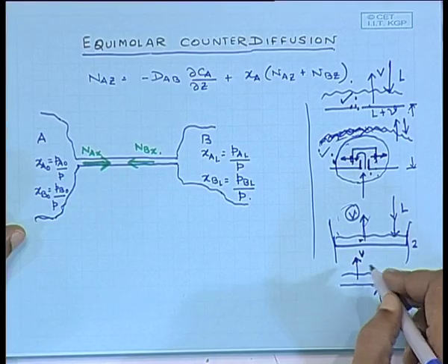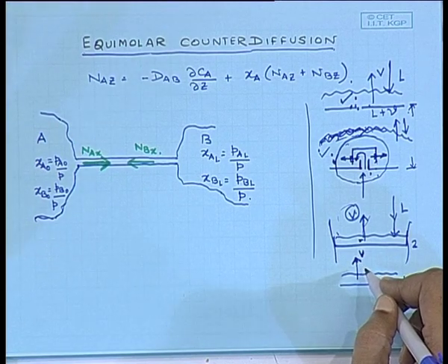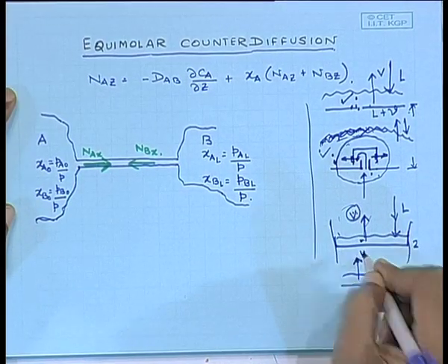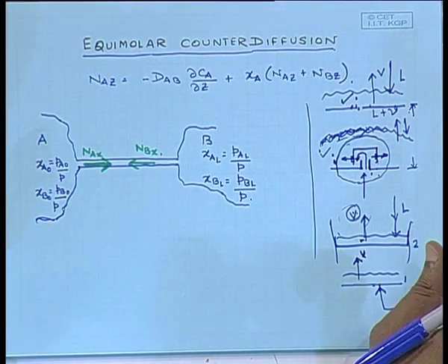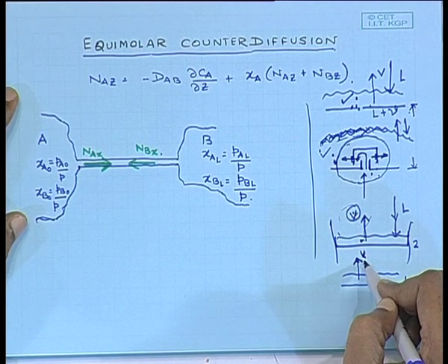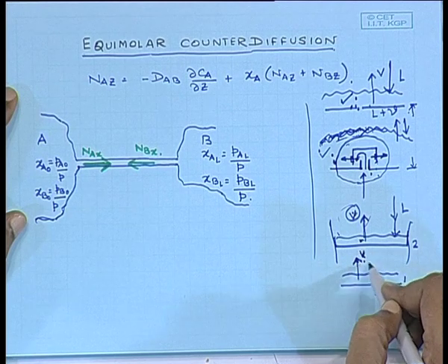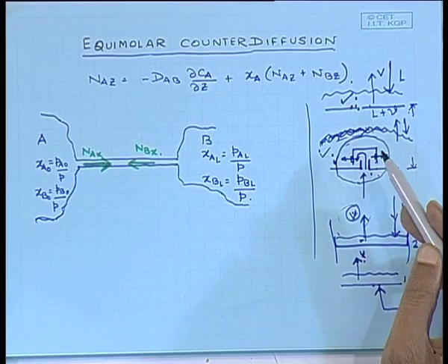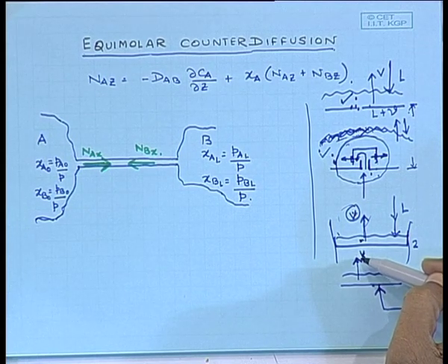The vapor which is coming contains, let us say, 2 components. It is the simplest possible situation, which is a binary distillation column, a 2 component mixture. Would the composition of these 2 be the same? Compositions are different. So, this is going to be richer in the more volatile component compared to this stream. Now, what is the latent heat of a stream? The simplest possible representation would be latent heat of component 1 multiplied by the fraction in which it is present in the stream, plus latent heat of component 2 multiplied by the fraction in which it is present in the stream. So, since these fractions are changing from stage to stage, you may not have exact equality in terms of